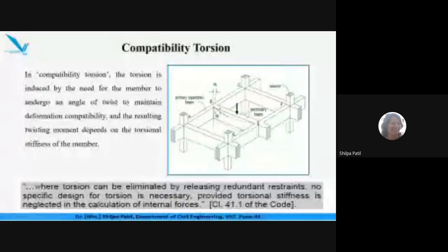Because at the joint, each and every member will try to develop an equilibrium. We want to achieve equilibrium, right? To avoid the deformation developed due to the bending of beam AB, it will be compensated by developing torsion in member BD, to achieve equilibrium at this joint B.